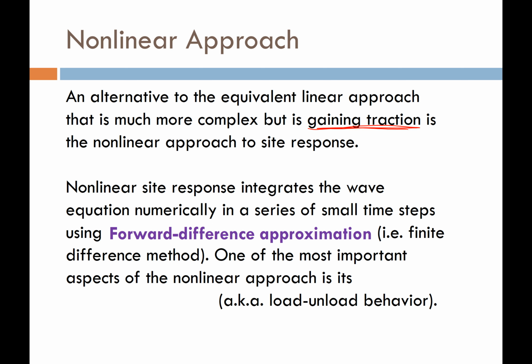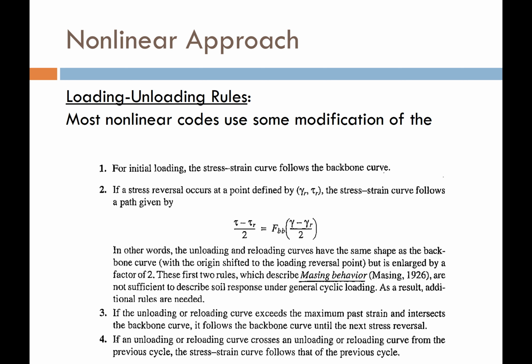But one of the most important aspects of the nonlinear approach is how it models the stress-strain behavior of the soil, how it models the constitutive model. I'm also going to add in here how it handles pore water pressure. Because pore water pressure is going to change as a function of the soil shear strain, and also the soil type and the relative density and the confining stress and all of those things. And so hopefully your constitutive model will incorporate some sort of pore water pressure generation model.